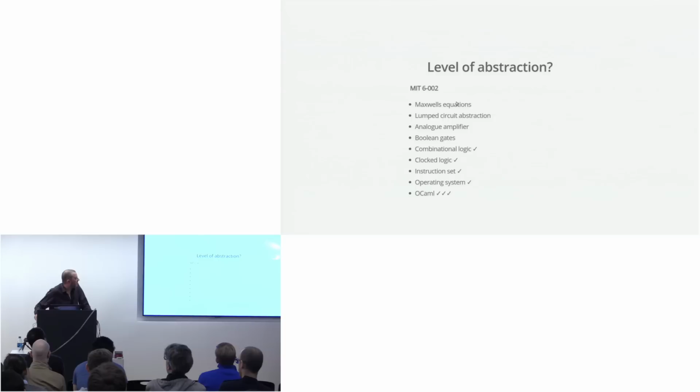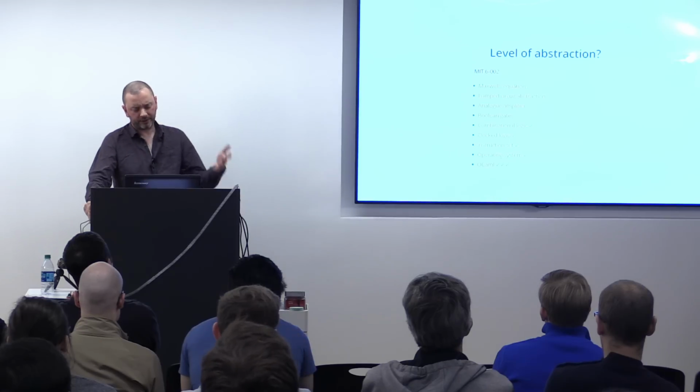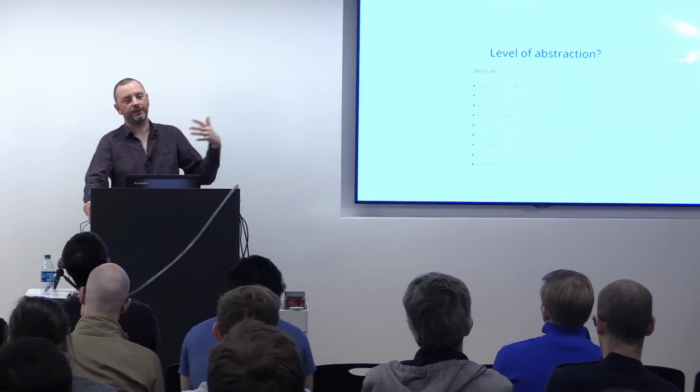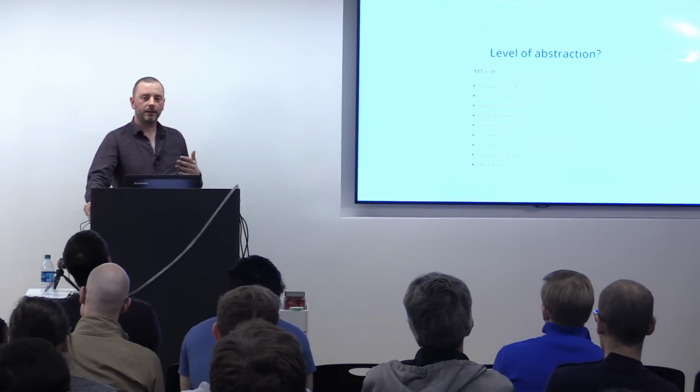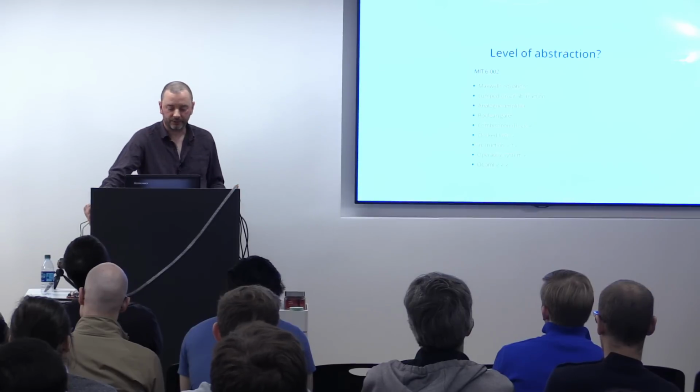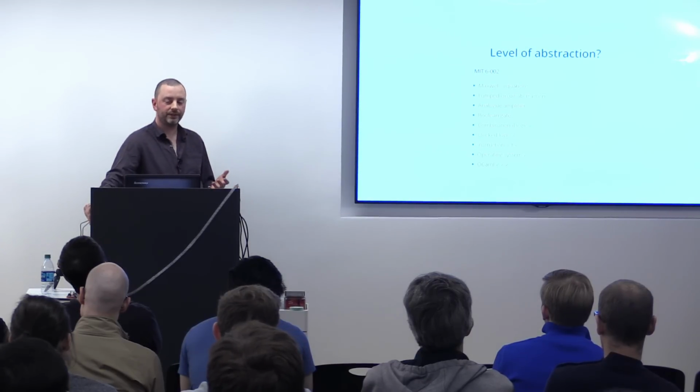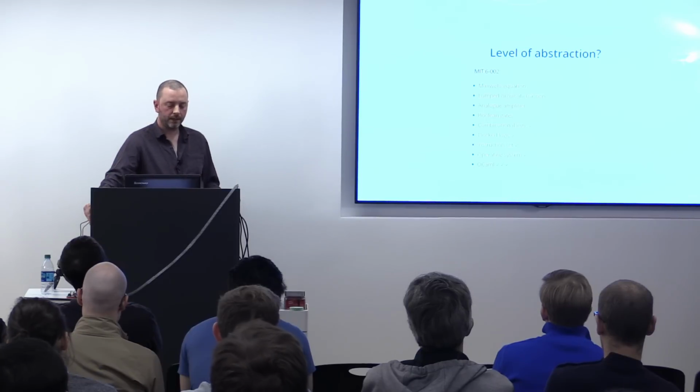But these days, with the advent especially of soft CPUs, you'll tend to get into more embedded programming as well to get these things running. So you start thinking about stuff like instruction sets and operating systems. Instruction sets in interesting ways: you might think that's just for a CPU, but you'll also build programmable state machines which have a kind of instruction set, so it overlaps there as well.